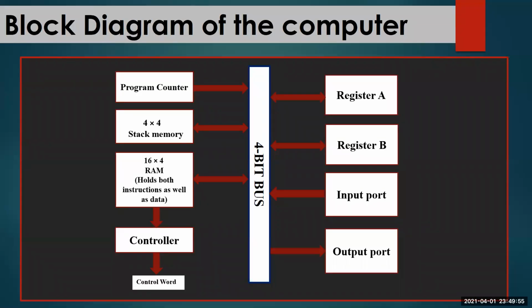We have limited ourselves to 4 bits. As a result, the RAM only contains 16 locations and each location can only hold 4-bit data. All the 16 binary numbers are assigned opcodes for instructions, and as a result, there are no opcodes left to extract data from memory, as that would require 8-bit instructions.